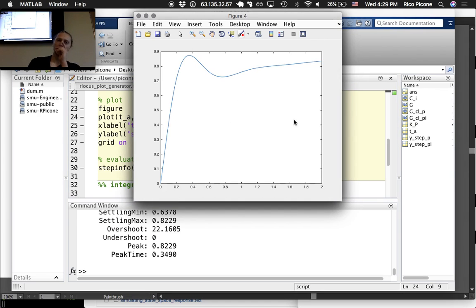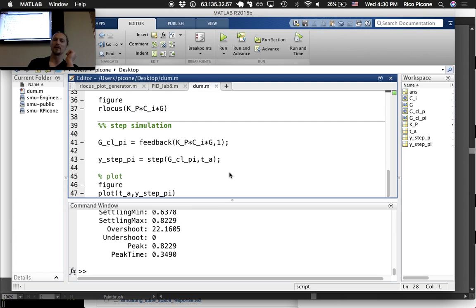Okay, so what we see, and this is pretty common when we do the compensator like this, is we get a pretty similar transient, and then we get this slow ooze to our steady state value. It's pretty slow though, right? We aren't in love with that, but that is how these compensators tend to be when you first design them.